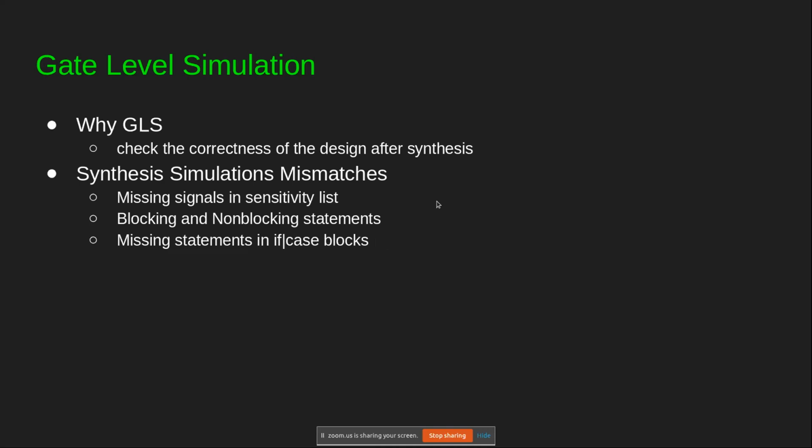The only difference is that instead of using your original Verilog code, you are going to use the synthesized netlist. Apart from that, since the content of the synthesized Verilog is now the mappings to the standard cell library, you have to give the Verilog models for each of the cells in the cell library as input to iVerilog as well.